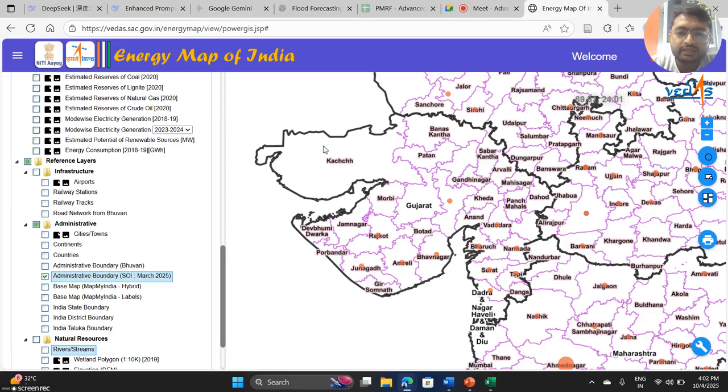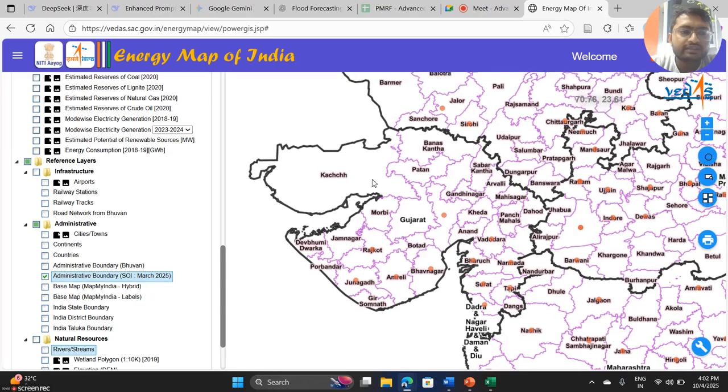Now you can mark the different points by hovering over them, and on the top right-hand side you can see the lat long. Whenever you click, you know the latitude and longitude of that location. Note it down. After that, go to your QGIS or ArcGIS and georeference this layer, and then you can digitize these values. If it is small, you can do it. If it is multiple, it will be difficult. It can be doable, but it will take time.